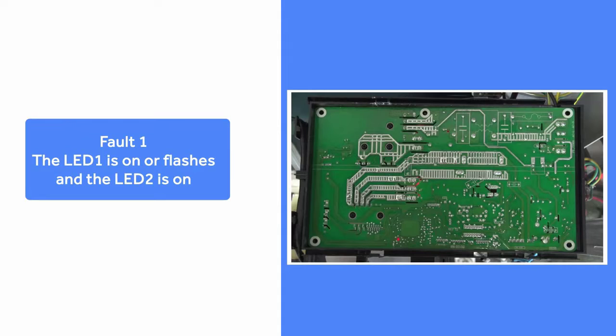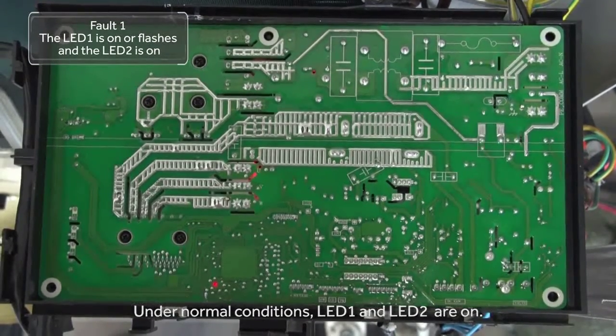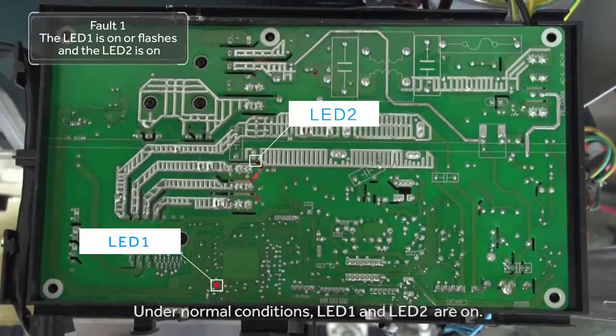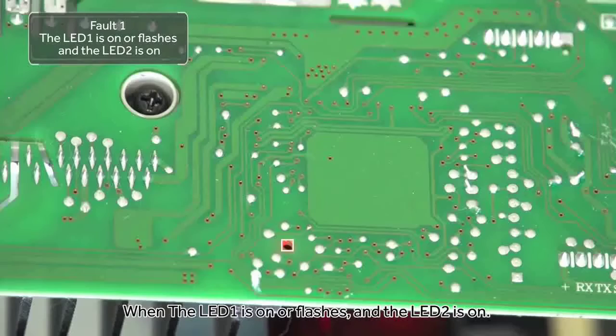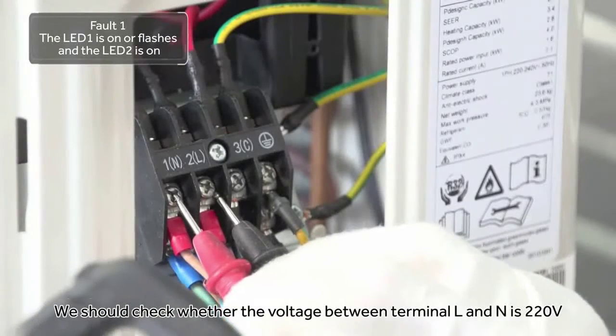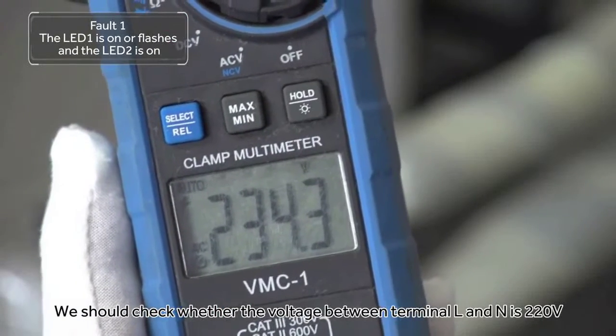Fault 1. The LED 1 is on or flashes, and the LED 2 is on. Under normal conditions, LED 1, the alarm light, and LED 2, the DC 310 volt power supply light, are on. When the LED 1 is on or flashes and the LED 2 is on, we should check whether the voltage between terminal L and N is 220 volt.